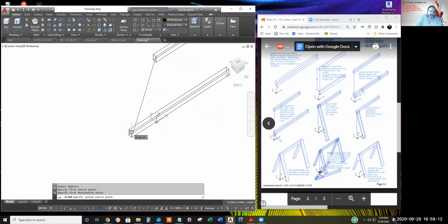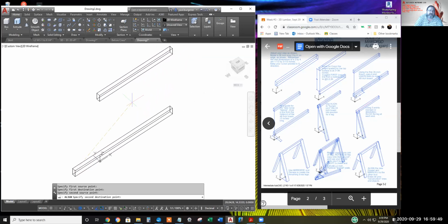I'll attach a second bungee cord, slightly weaker, to this corner. Now I want it to appear about right here, but that ain't an Osnap. So I could type NEA, to invoke a near point Osnap override. Instead, I'm going to slide all the way up an Osnap on the midpoint. Now, as soon as I pan so I can see the triangle at the midpoint, I expect this black bungee cord will disappear. Let's see. Yep, there it goes.